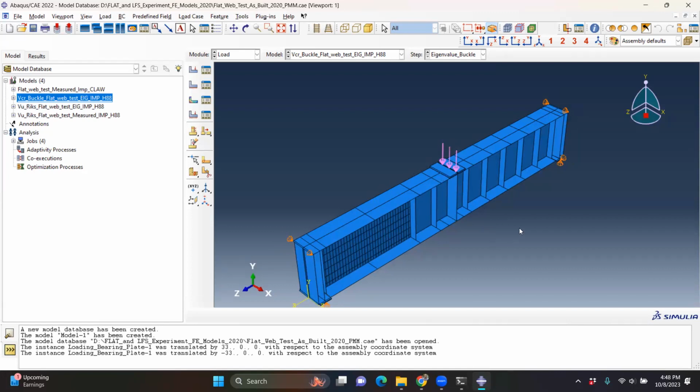It's just creating a solid element, partitioning it correctly, and then tying solid to shell element. Remember, when you're tying a solid to a shell element, your solid element is the main surface and your shell element is the secondary surface. And make sure you also partition the flange or your shell element so that you are only selecting the area that needs to be tied to the solid element without having the need to do any tolerance transformation.